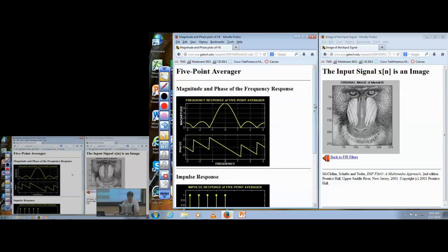The averaging filter is a 5-coefficient filter. It's unnormalized. The DC value is 5. I have 4 zero locations, so I have 2 positive frequencies that get eliminated, and 2 negative frequencies that are the negatives of the positive frequencies being eliminated. So I have 2 frequencies being removed completely by the filter, and we cannot recover them once they're removed.